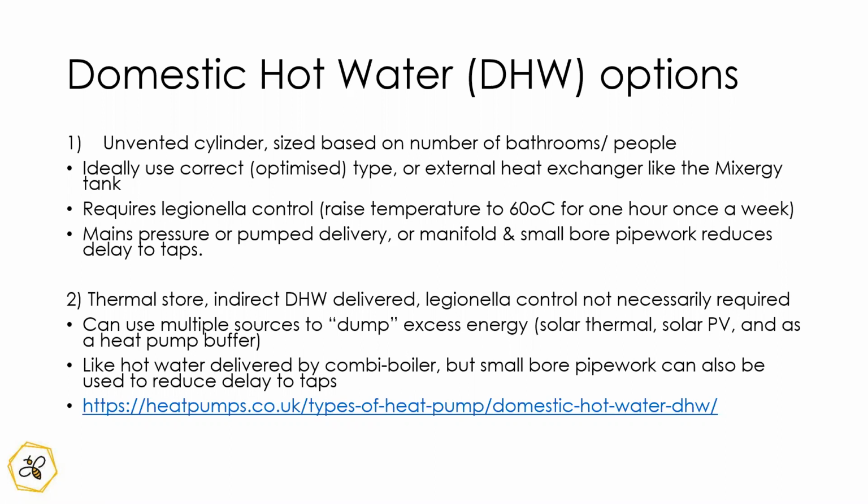It will need to be at a slightly higher temperature than the water you want out. So say you want to always deliver hot water at 45 degrees, you might need to keep it more towards 47 or 48, just so you can get that heat transfer. The hot water is literally pumped through pipes or a coil inside the thermal store, and is delivered a bit like it would be by a combi boiler, so mains pressure and instantaneous hot water.